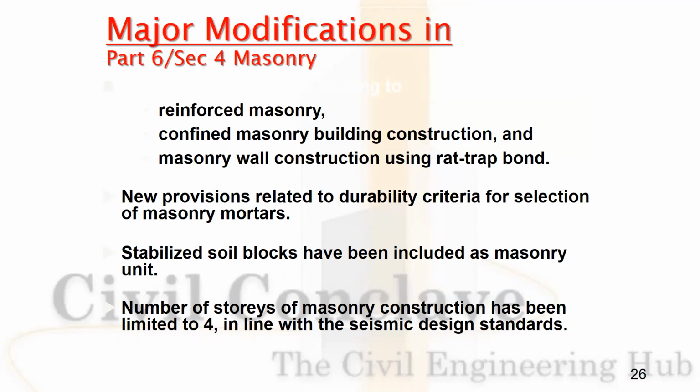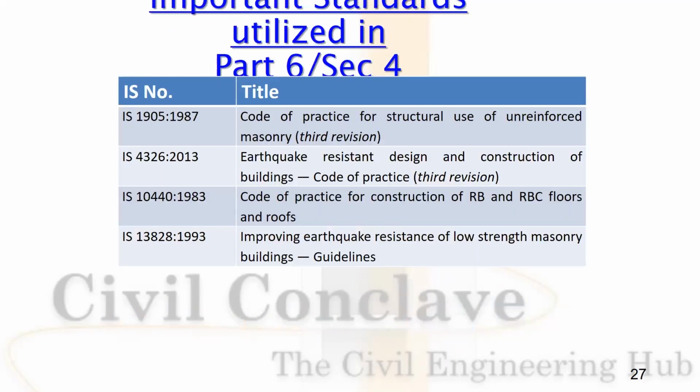Masonry, reinforced masonry, confined masonry in building construction, and masonry wall construction using rat trap bond. New provision related to durability criteria. Stabilized mud masonry included as a masonry unit. Number of stories of masonry construction has been limited to 4 in line with seismic design standard.